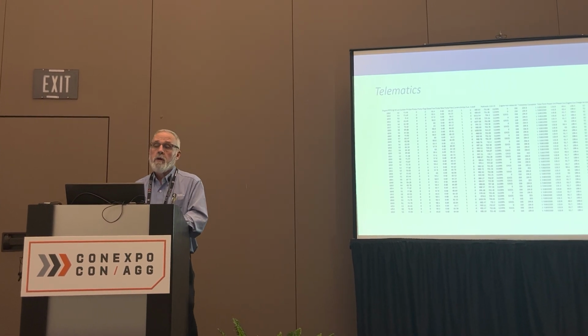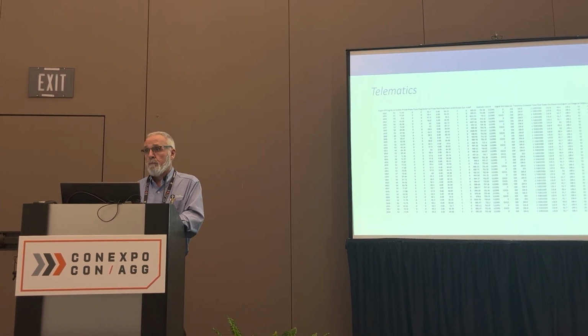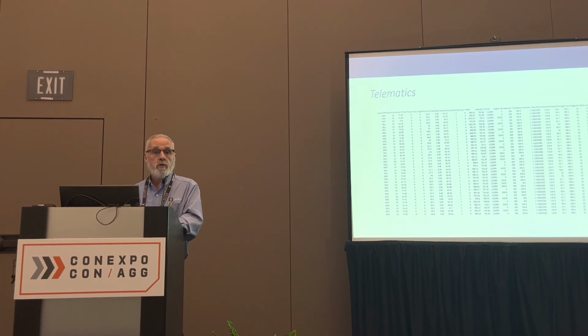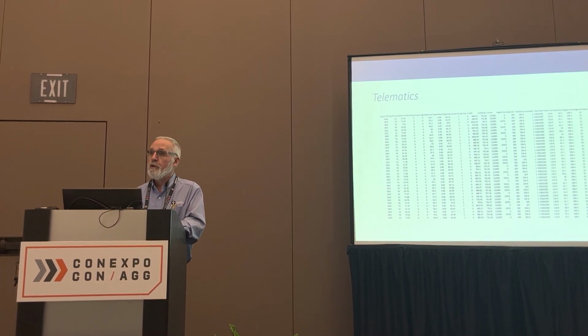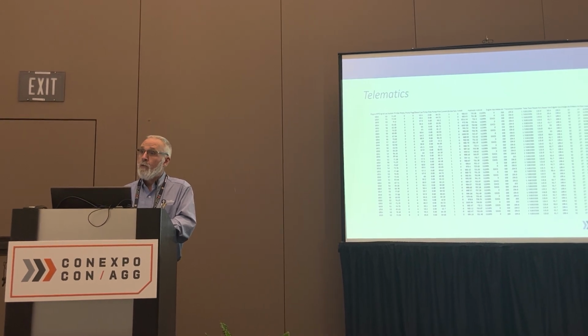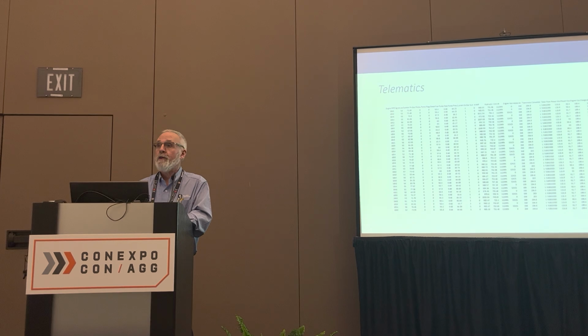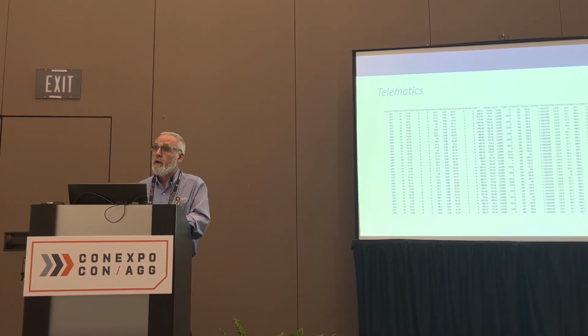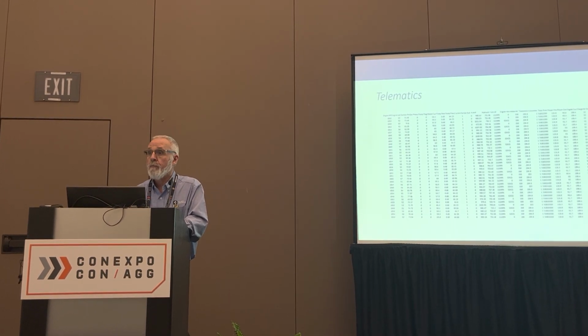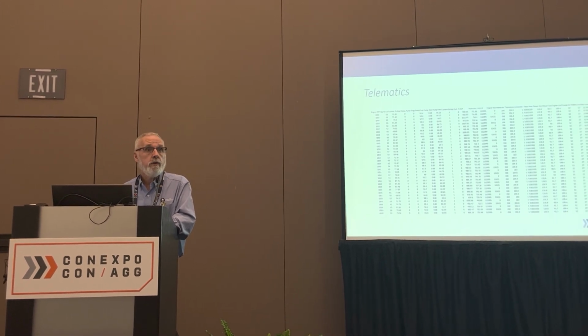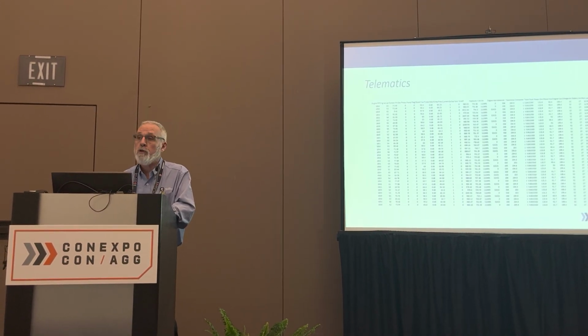But then I got a telematics download from that customer, and we reviewed it, and sure enough, there were faults with injector number 3. And now we can say there's fuel dilution. We suggest you start inspecting with injector number 3 based on your telematics data. And it really narrowed down the troubleshooting and the time spent troubleshooting for the customer.